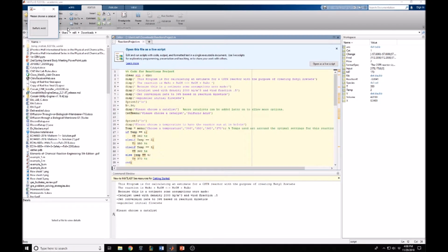Some of the other chemicals involved besides sulfuric acid, which is seen up here, are acetic acid, N-butanol, and N-butyl acetate. All of these are flammable and need to have a chemical powder for small fires and an alcohol foam system for larger fires. For small spills, you need to dilute it with water, then mop it up with the appropriate waste disposal. For larger spills, absorb using dry earth and non-combustible inert material. Then dispose of this according to the local, state, and federal regulations.